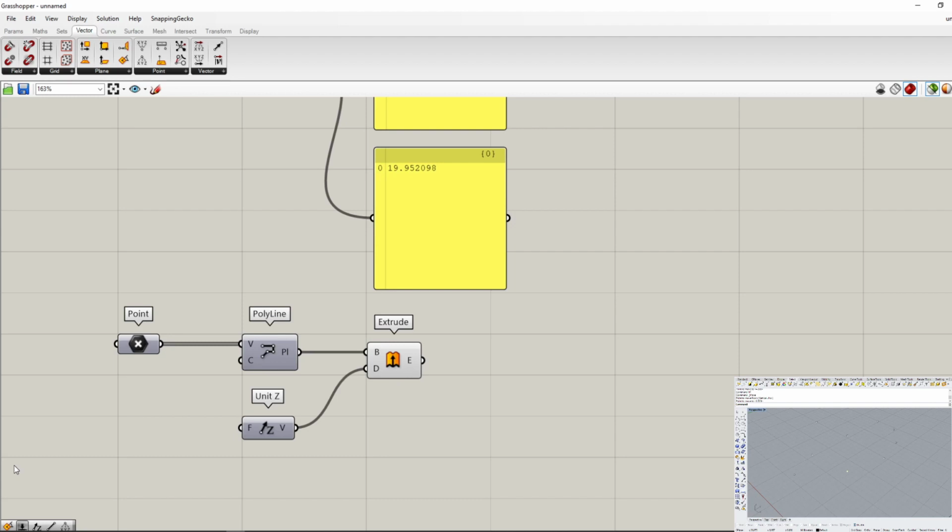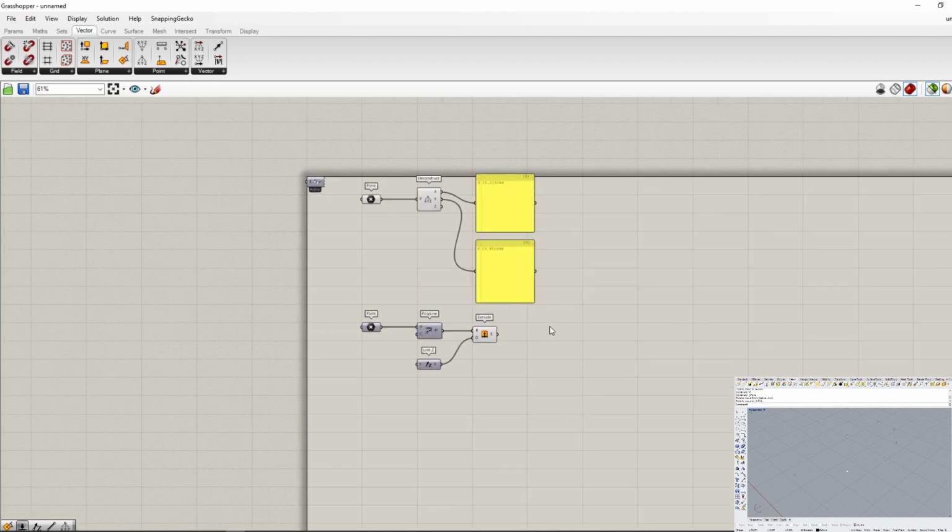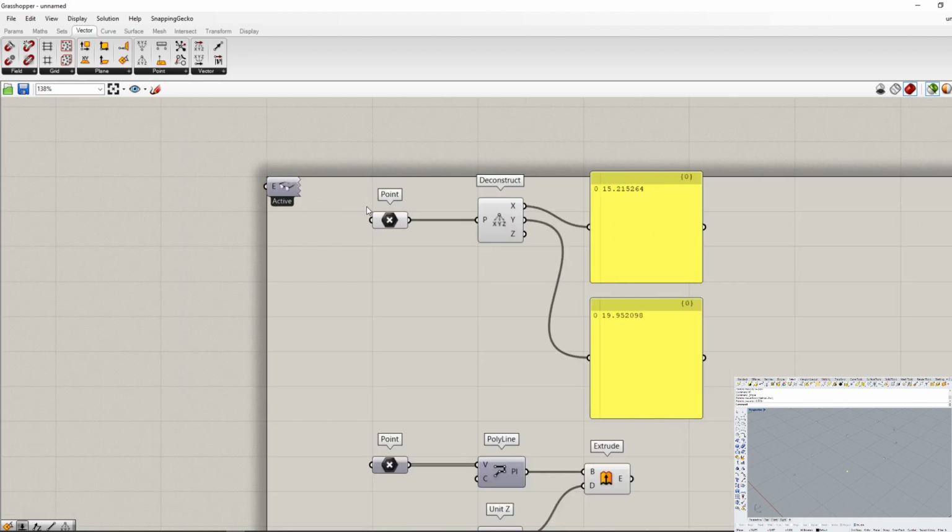So that's pretty much everything for an introduction to the Grasshopper interface, which is a bit of a mouthful, but let's just quickly go through everything we did. So we've explored how to open the window, how to bring geometry, just points mind you, but geometry into Grasshopper.